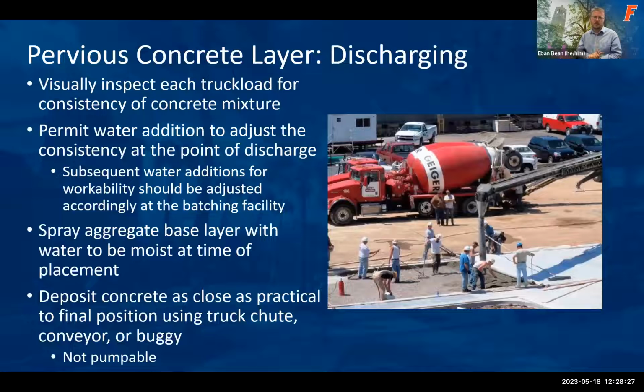With discharging and installation, number one, porous concrete is not pumpable. Okay, so you're not going to be able to pump it. You've got to place it in there. Good idea to spray the aggregate base, that choker course, with water so that there's some moisture on the bottom side of that and it's not just taking the water out as it's curing.